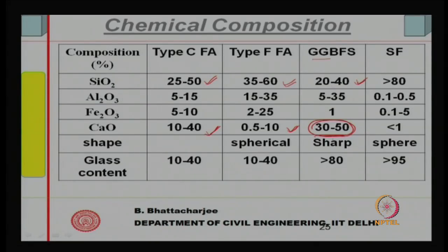Now, these slags usually float over the molten iron. So, iron is drained out from the bottom and slag is taken out from the top, in molten state, then it is granulated, etc. Therefore, it will have higher lime, because that was added to remove the clay, and you have 30 to 50% of the lime, but then silica is less.